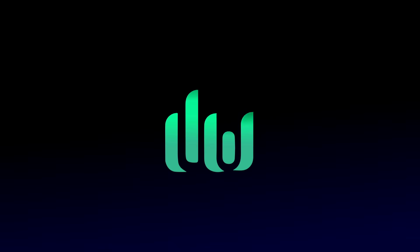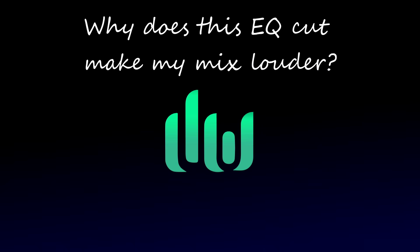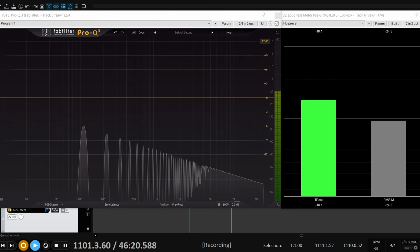Okay, my second point about phase shift. It's a perennial question, which the FabFilter team get asked regularly, I gather, and which constantly pops up on forums and social media. Why does this EQ cut / high-pass filter make my mix get louder? There's a mistake built into the question, in fact, which I'll demonstrate with a sawtooth wave, and I'm showing both the peak and the RMS levels on this meter.